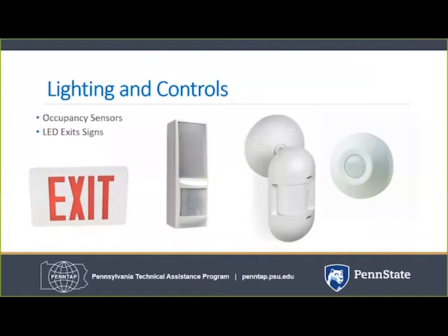Most lighting is not needed as often, but relying on individuals to switch lighting off and on as needed may not be practical in every setting. Occupancy sensors in restrooms, offices, conference rooms, and warehouses can provide significant energy savings with or without a lighting upgrade.